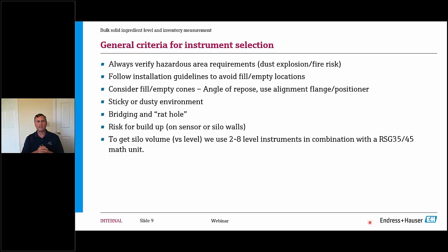Solids also have a dynamic where you have a filling cone, and also you're going to have an emptying cone. So this is a dynamic that you need to keep an eye on. You may need to see, okay, where am I locating my level sensor to make sure that I get the measurements that I'm looking for here.